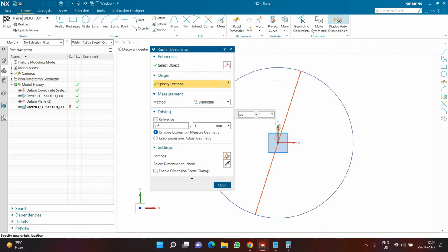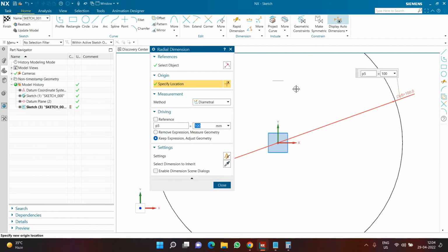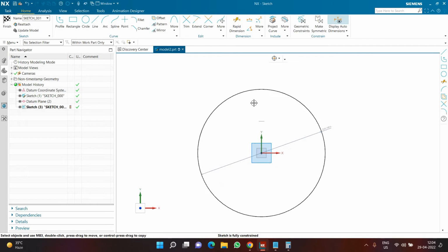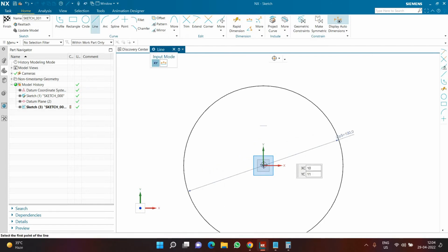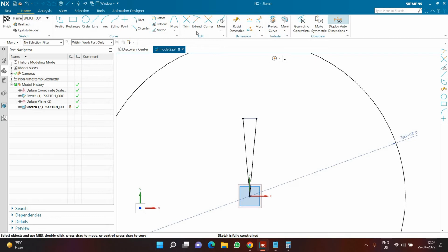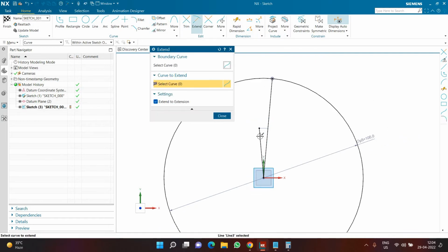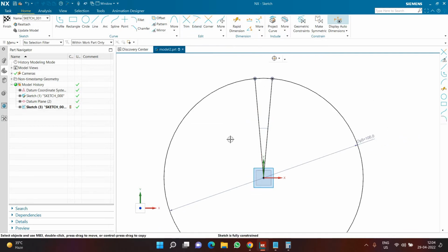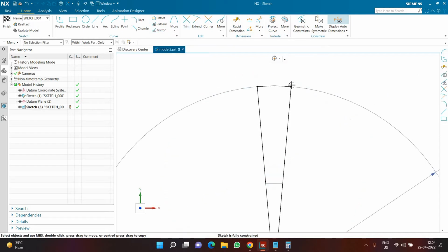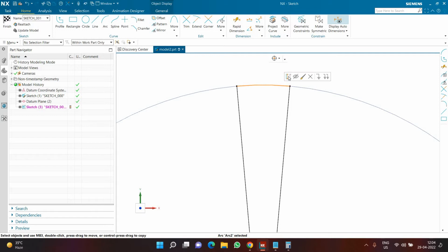So let's say you can decide whatever dimensions you want after completing this video. And this video can be followed by any beginner or any advanced person, because it includes all the sketches and everything. So now I'm going to create a line from here to here and then from here to here, okay, and then I'm going to extend the line all the way to the circle, like the way we did in the previous one. I'm going to use the trim tool to get rid of the extra part of the circle. Same thing, only the diameter is 100.